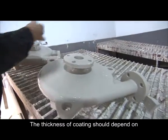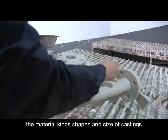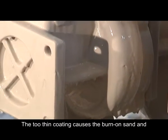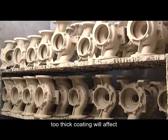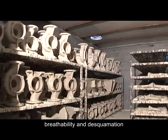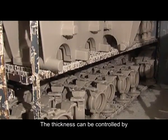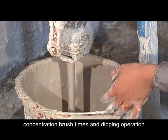The thickness of a coating should depend on the material, kind, shapes and size of castings, usually in the range of 1 to 2 mm. Too thin a coating causes burn-on sand and decreases the protective effect. Too thick a coating will affect breathability and cause deformation. To obtain qualified castings, it's better to adopt thin coating. The thickness can be controlled by concentration, brush times, and dipping operation.